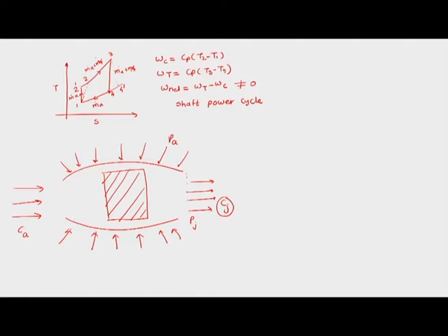So we might have an objective to work upon maximum thrust, we might have to work upon optimum economy in case of cruise or steady flight. So these objectives need to be thought for, and these objectives would have certain quantifications, and those quantifications need to be assessed while comparing two Brayton cycle based power plants.